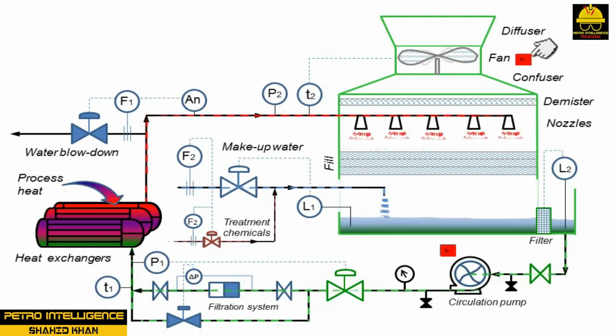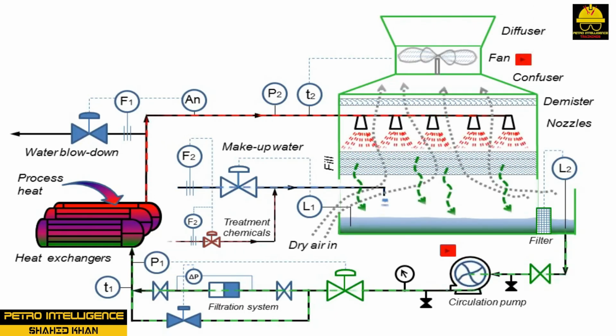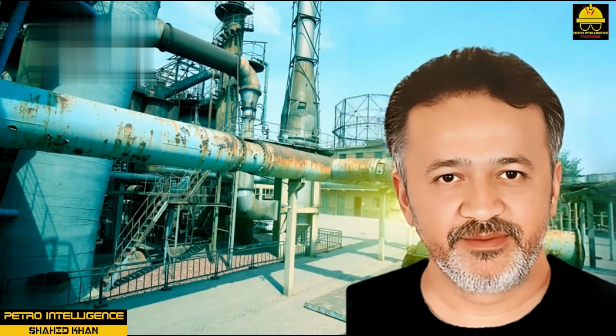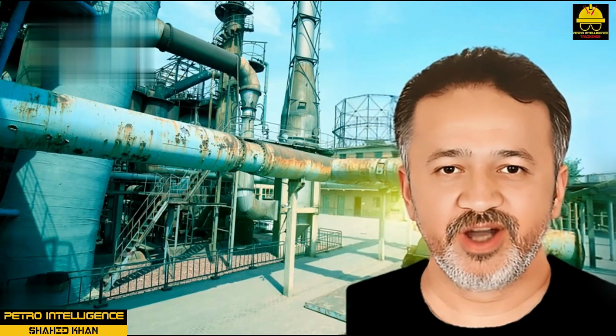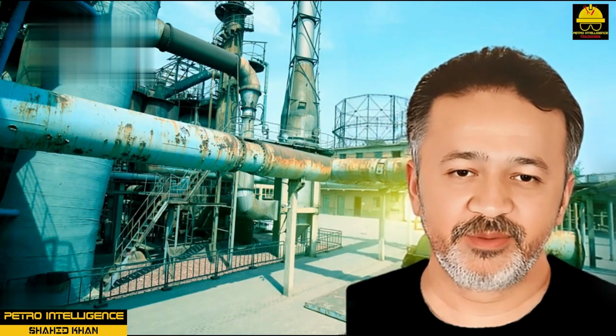Sidestream filters may be used to remove airborne solids such as dust and sand and contaminants introduced via the cooling tower makeup water such as silt, organic matter, and waterborne organisms. Each filter is sized to handle the full flow while one filter is backwashing or out of service. The side-stream filters operate automatically under gravity flow and are of the self-contained backwash type.